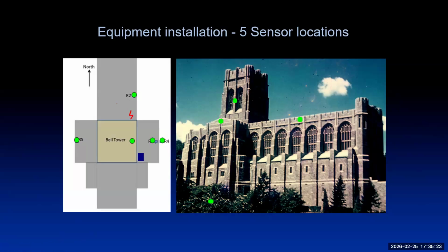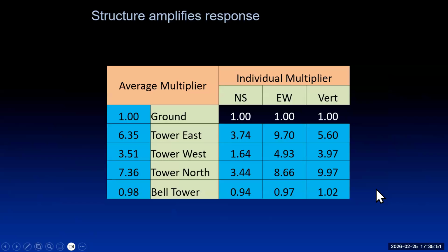So we actually said to people, you mustn't do this. We've measured down the ground and we've got a 12 times amplification up high. And so they had a look. They found the cracking inside that area between transept and the nave, and that's why the Army Corps of Engineers decided that they would say thank you to us. This is the response in those different modes.